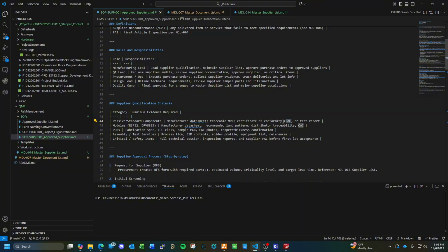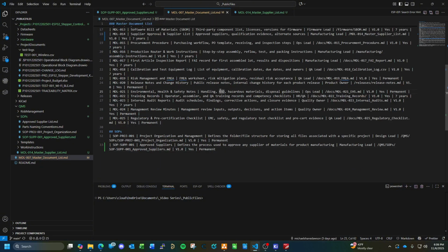We did source them from, say, Analog Devices or Texas Instruments. So always make sure you can get COCs. Make sure you can get lot numbers to do tracking. We'll get to that down the road. Those will be processes and other documentation, other methodologies we'll have to do. But for now, we're not going to worry too much about that.